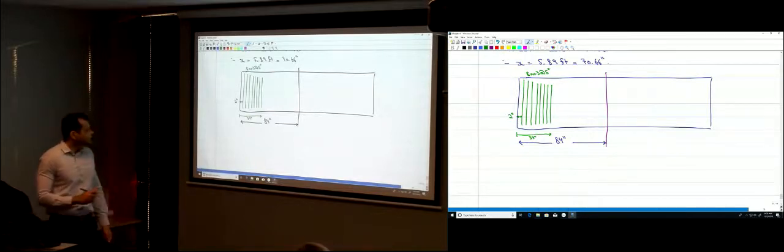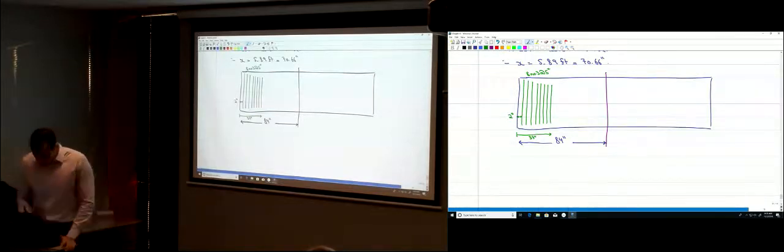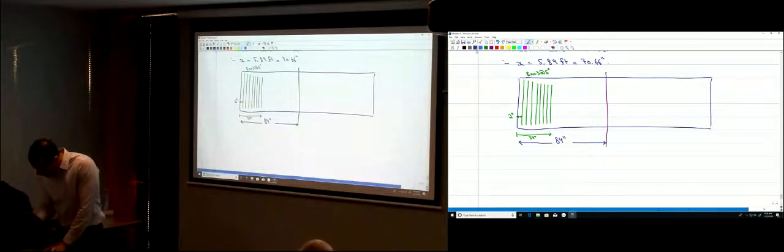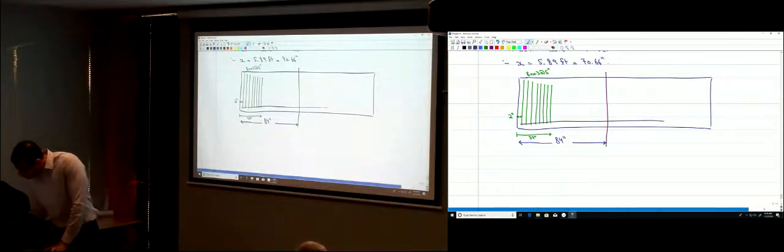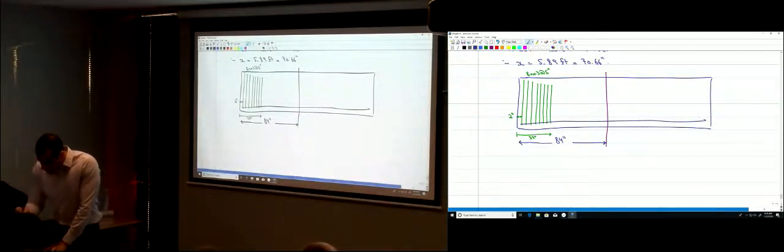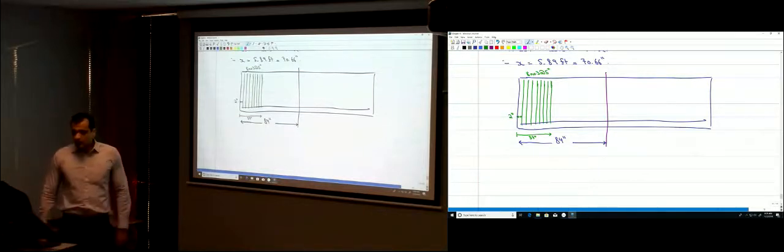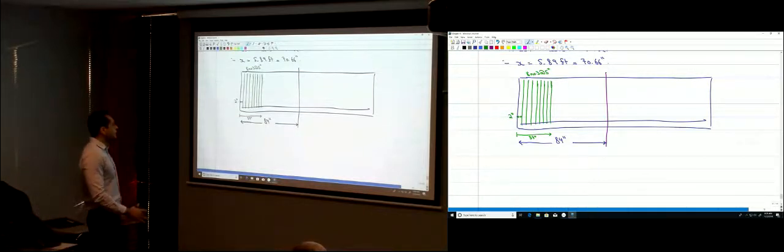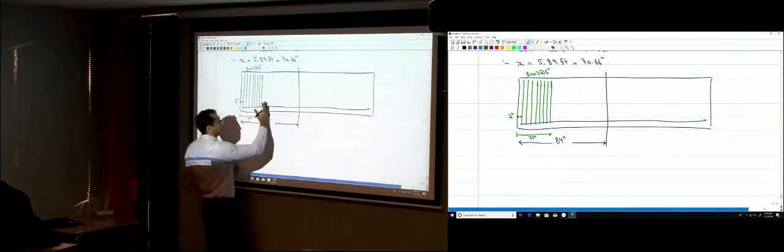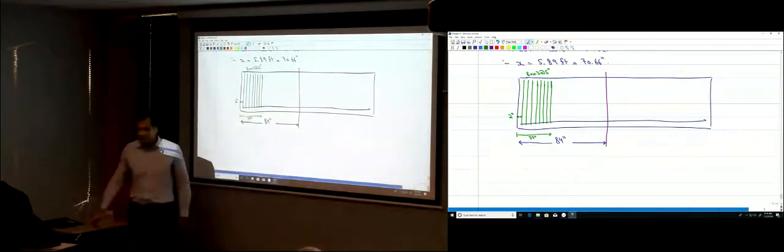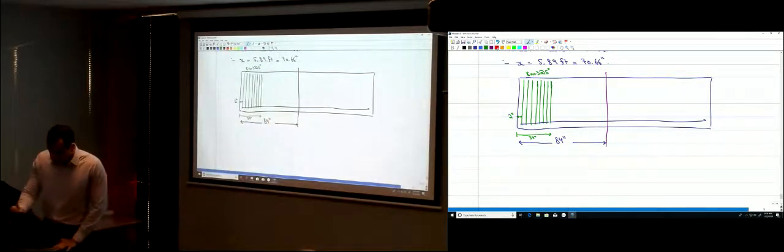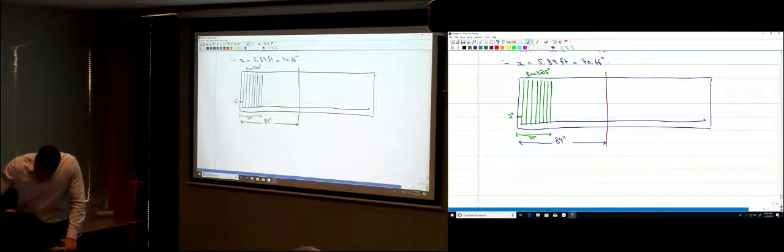Okay? The longitudinal bar looks like this. This is the longitudinal bar here. Okay? And your stirrup definitely is going to go to the end here. Okay? And then now I need to provide the number 9 spacing, right? So I'm just going to provide a spacing of 9 inches.